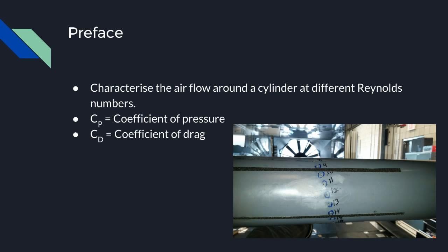How we collect the data. The tunnel was run at 4 different RPMs, creating 4 different Reynolds numbers over the cylinder. The scanner valve connected to all the ports on the cylinder, logging the pressures on the laboratory computer. Unfortunately for our group, there was an issue with this data acquisition, but fortunately, Kyle, our lab TA, supplied us with accurate data which we used for data analysis. This data was then uploaded to MATLAB, where we generated the CP, CD, and further information for the data analysis.